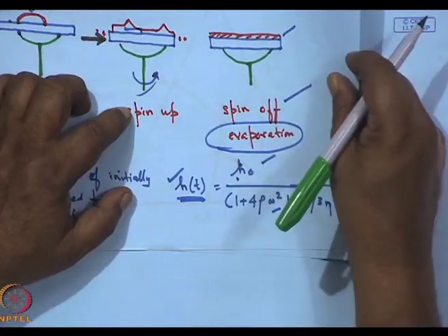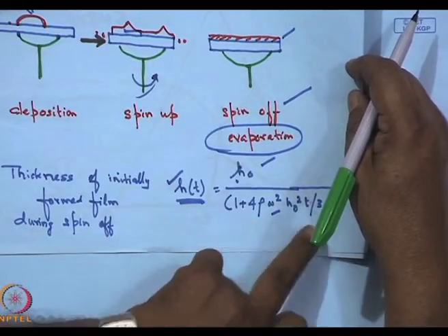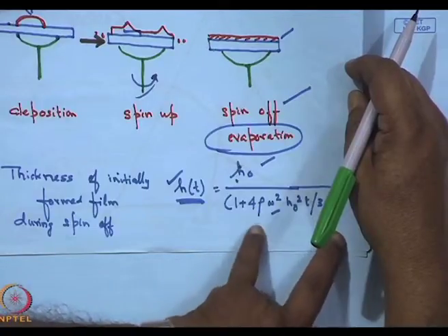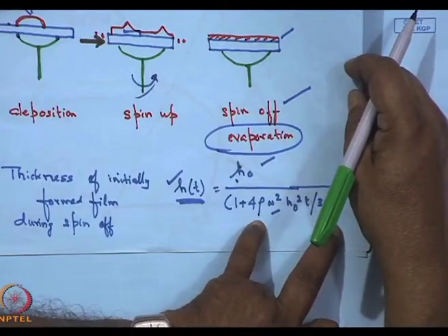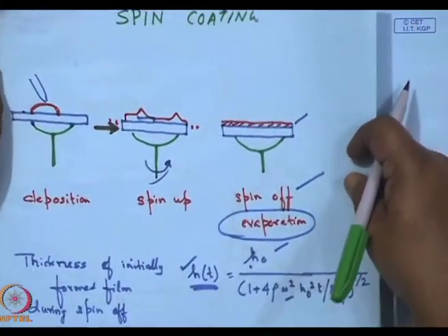So, here we need to control the density, that is the solids loading, and the viscosity. These two are in our hands. The adhesion property is something that we can use by changing the type of mixtures. For example, if an alkoxide derived coating is made from, say, aluminum nitrate, what we will have is a very, very good aerogel.